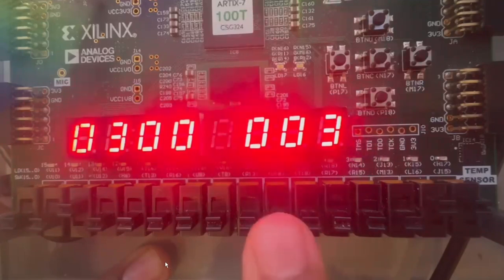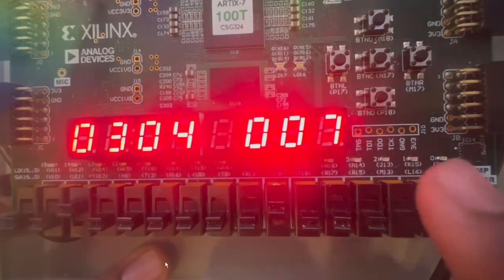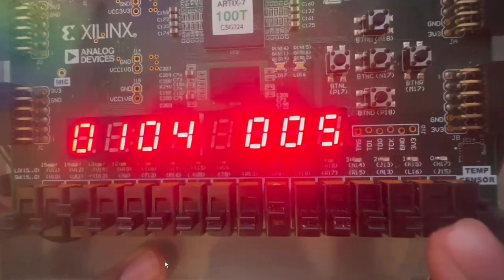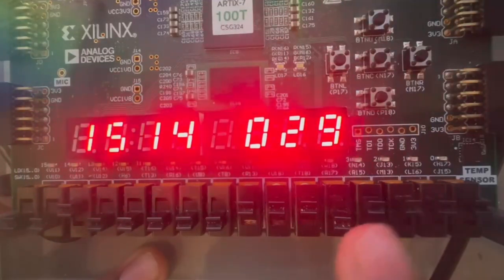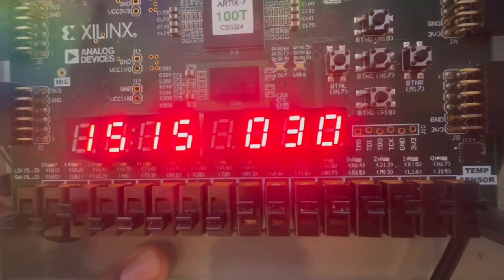As you can see, addition is currently selected with 001, and it's adding up inputs A and B, converting them from binary to decimal, and then displaying that decimal value on a 7-segment display. Since the inputs are 4-bit values, the max value for the input for each digit is 1111 in binary or 15 in decimal.